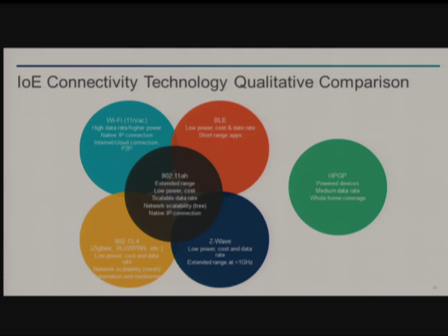Okay, so where are these PHYs used? Just to summarize, BLE and Bluetooth are very low power, modest data rate, and tend to be short range. Wi-Fi has very high data rates. You can get very good range, especially with repeaters, but they're not as power friendly as the other devices. But if you need the throughput, you need to go there.